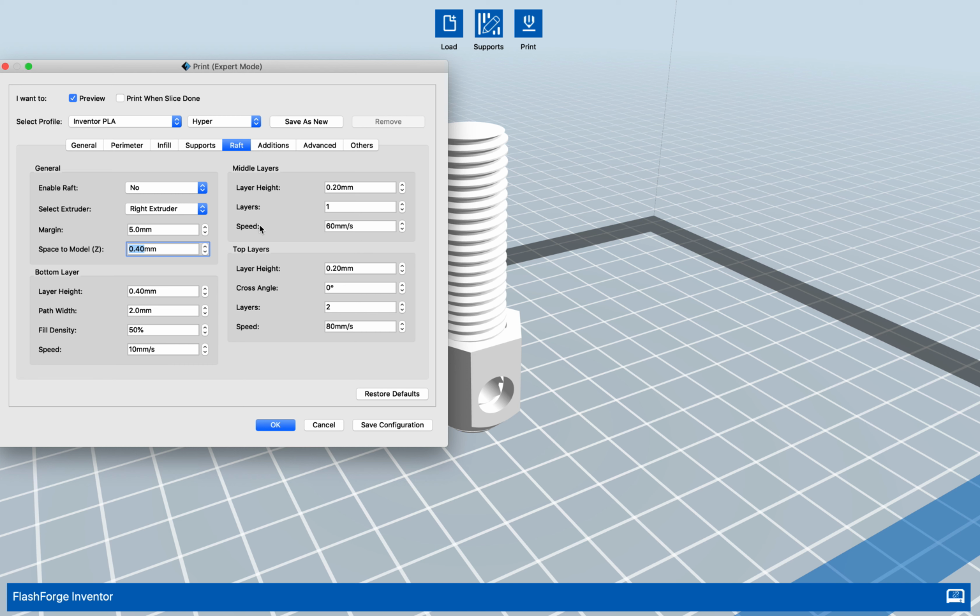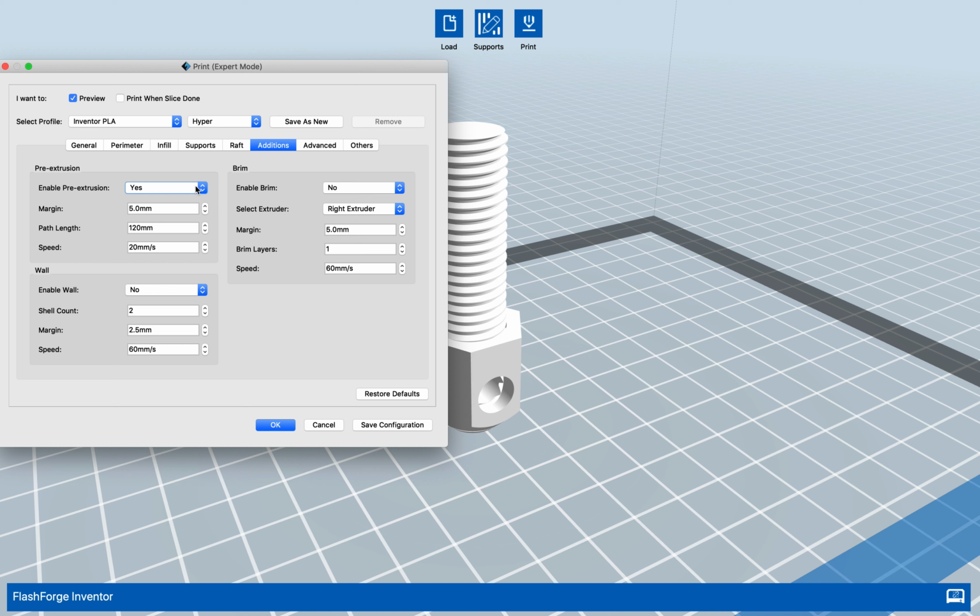They all stay the same. And additions, and that stays the same there. But over here you see an icon called brim. Now brim is basically a small circular pad that helps any tree-like structure grip to the table it's been printed on. So change that from brim no to yes, and let's go then to advanced